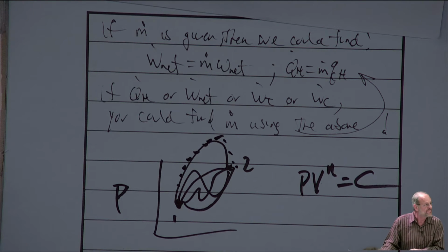I remember one of the thermal problems, and there's heat of fusion. Do we ever use heat of fusion? When we talk about fusion, we're talking about the phase change between a solid and a liquid. I haven't really gone into any problems like that. All the phase change problems we've looked at involve vaporization, so we can say heat of vaporization. In fact, hfg, the difference between hg and hf, is often called the heat of vaporization.